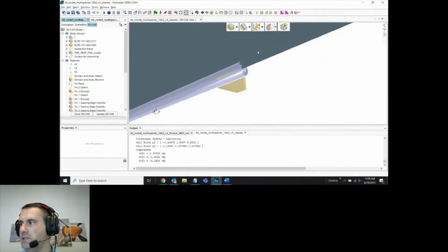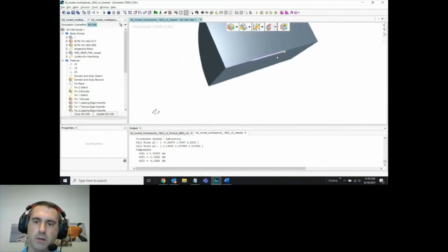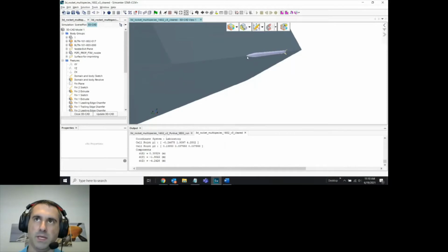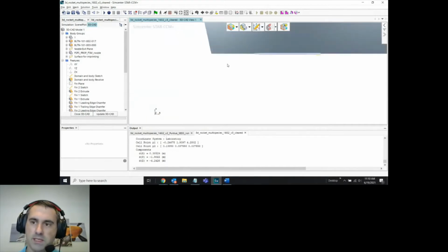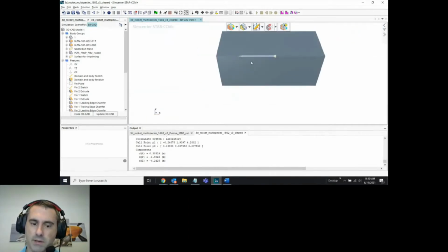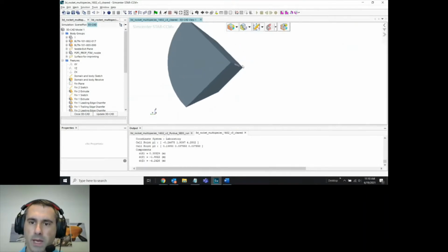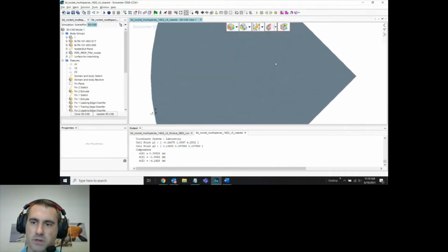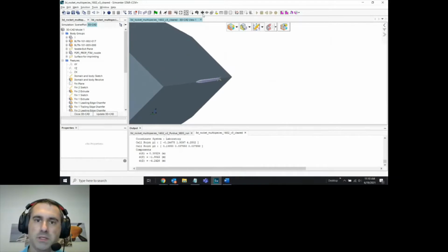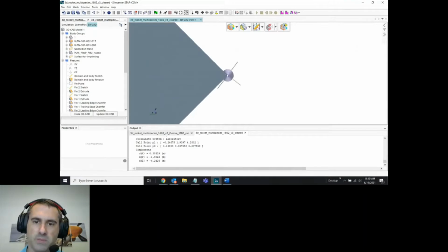And now the other thing that I need to do is move this so that the fins for this sit in the same location as the fin that I have in my CAD. Just as a side note, to do this a little bit easier, there are hotkeys. Like if I hit T, that's the top view. F is front, S is side. So I want to get a front view. Now, this doesn't really help me too much because I can't get directly head on to this geometry. You can see now I'm kind of left of it, now I'm kind of to the right of it. So to change that, I'm going to come up here, go to projection mode and parallel, and now I'm always directly top down on it.